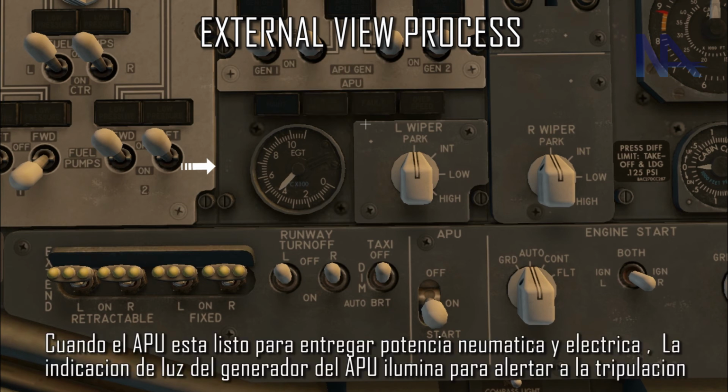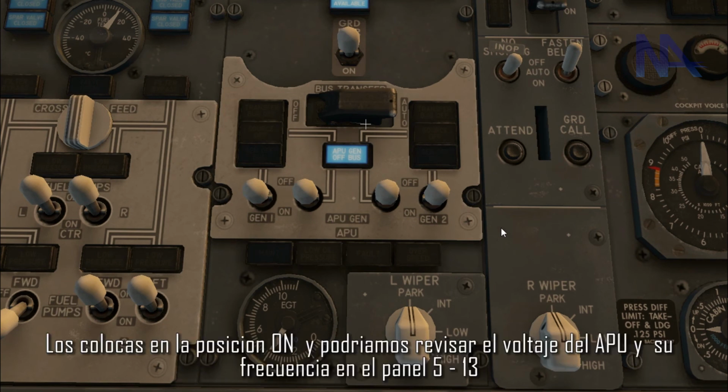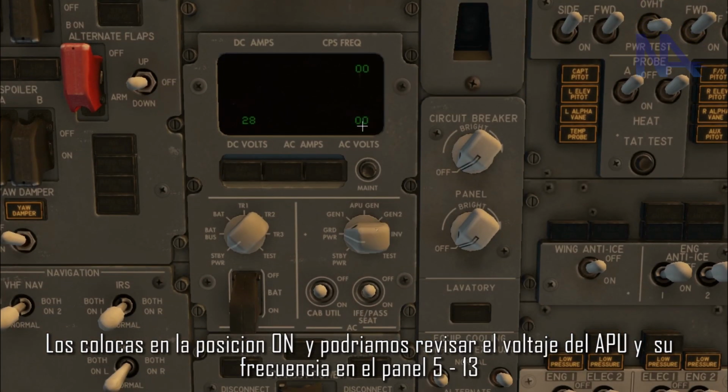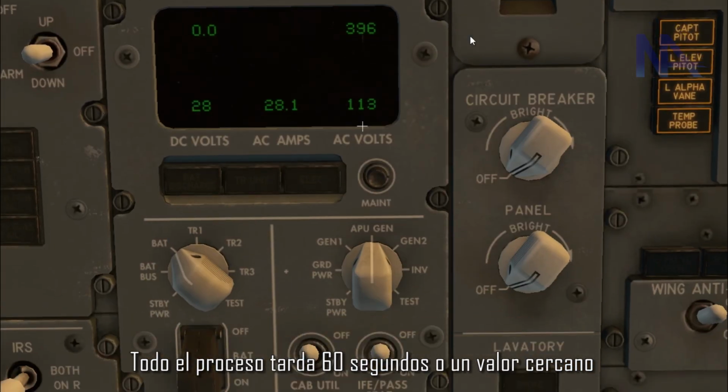When the APU is ready to give electrical and pneumatic power, the APU generator lights illuminate to alert the crew that electrical power is available now. You put them in the on position and we can check the APU's voltage and frequency on the panel P5. All the process lasts 60 seconds or a value approximate to that.